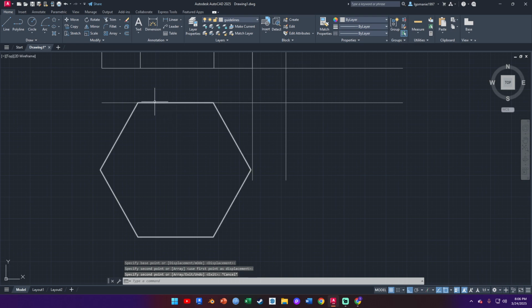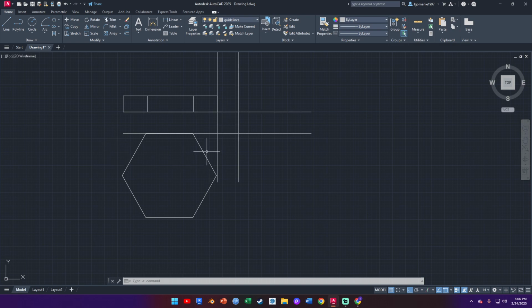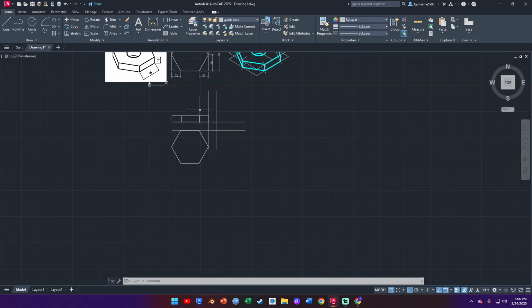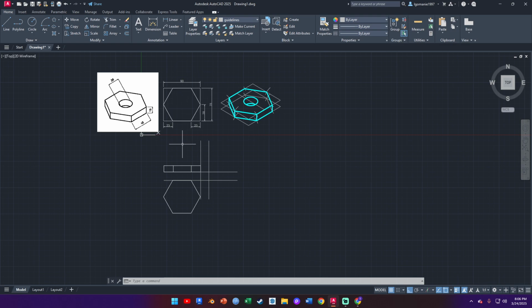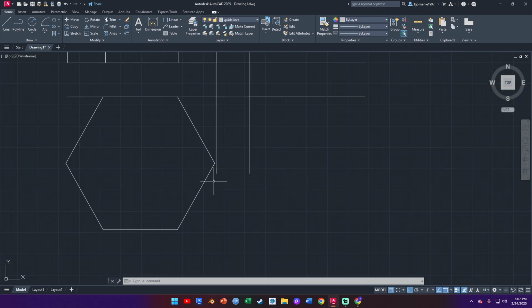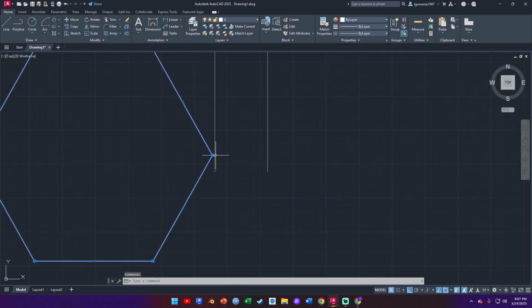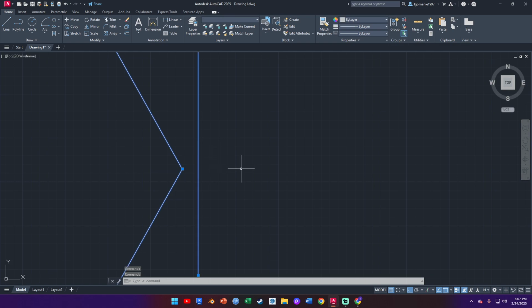But when I move it using the midpoint, you come across an issue, and I specifically did that to show you what you can do when you have these issues in AutoCAD. Your plan view is supposed to be touching this 20 mm guideline.